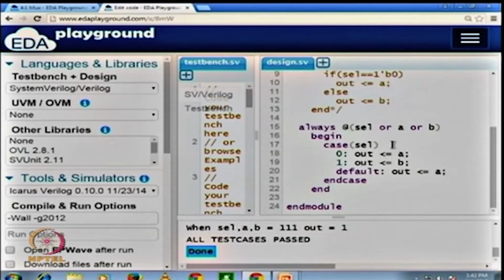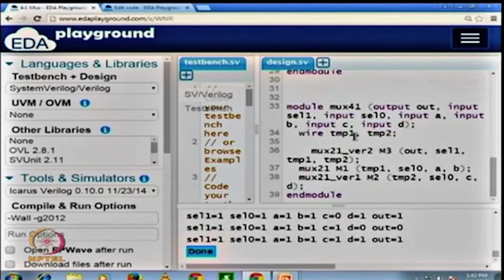One is we have seen something called the always block, and the always block is something that actually goes inside the module, and you can actually have what are called sequential statements inside. I'll talk about what this notion of sequential is. This is not the same as sequential design. There is something to do with the order of execution of statements inside an always block, and we also saw how we can write different things and mix them together when I talked about multiplexer 4.1.